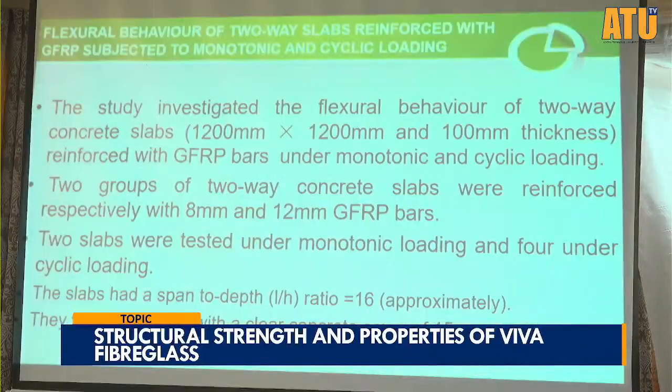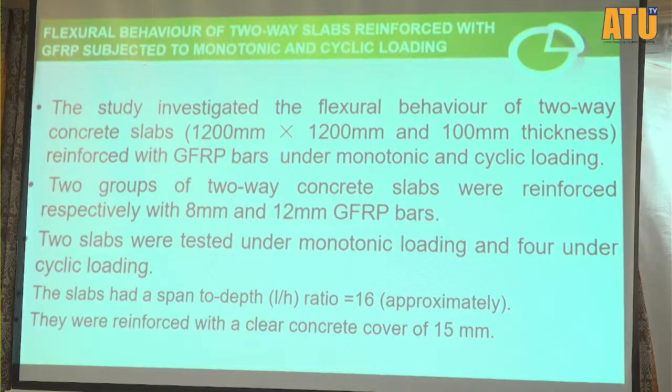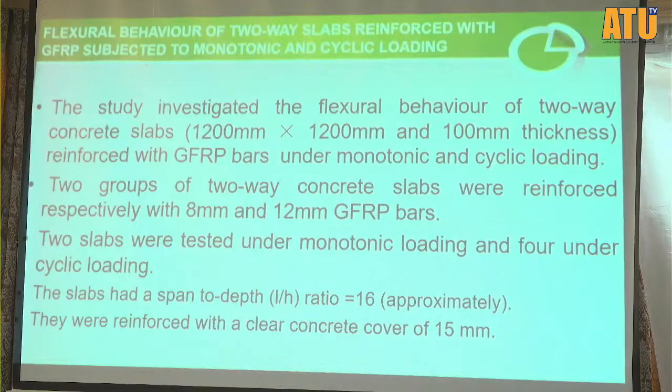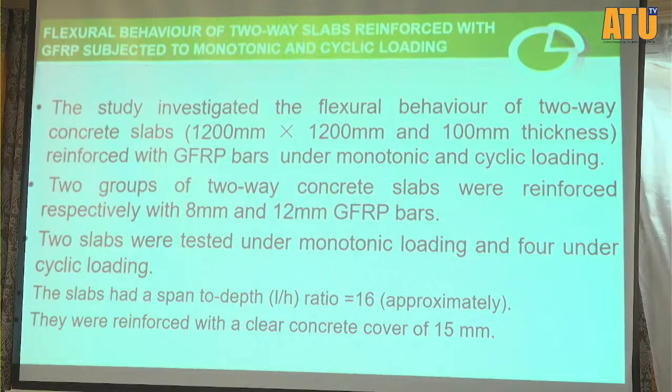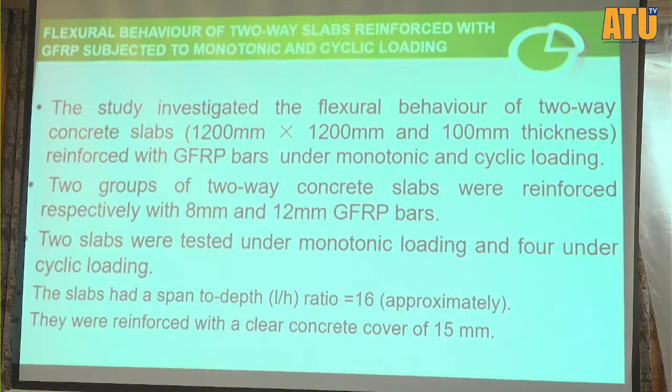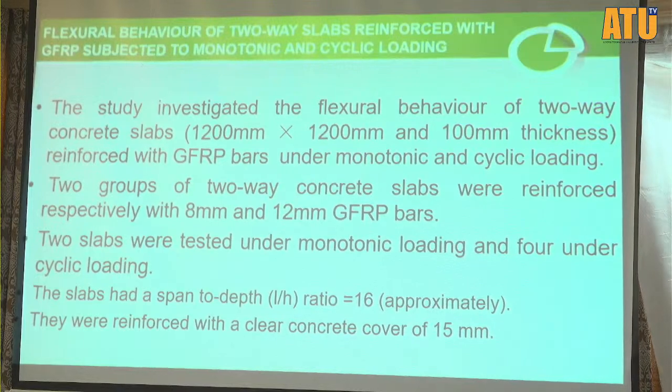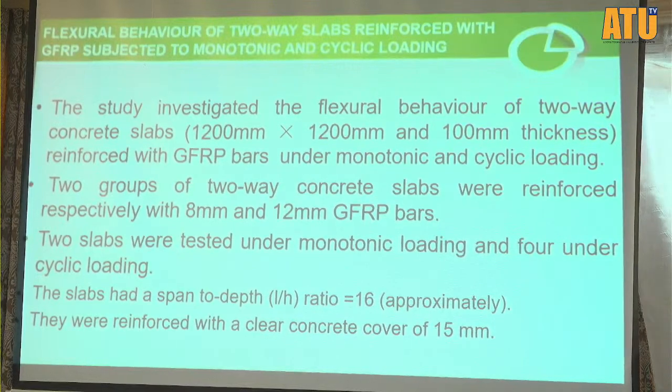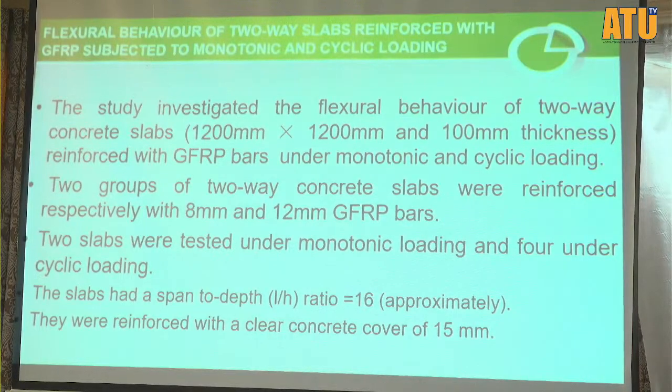The last one is a two-way slab. When you are designing those in concrete structures, we have one-way slab, we have two-way slab. If you say two-way slab or panel, it means the ratio between the length and the breadth, or the width, is not greater than 2. It's at most 2. That is the two-way slab.